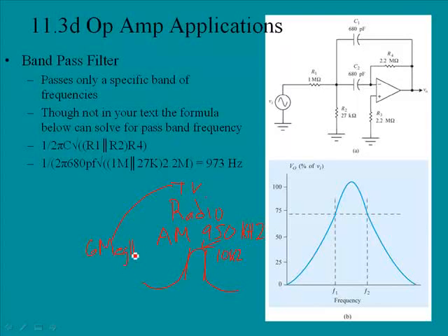In television, at least in analog television, the band is actually quite wide. It's 6 megahertz wide, and so you'll have this band of frequencies, and that contains the audio and the video and the color information. Takes quite a bit more data than does radio, which is only voice. And then if we went to FM, we'd find that this is actually 200 kHz wide, because FM is going to have a better sound quality. At any rate, these are just some examples of devices or systems that would utilize a band pass filter.